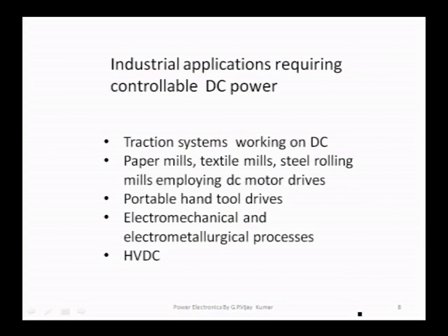So, that is why we are studying phase controlled rectifiers. If somebody asks why you are studying all these things, phase controlled DC power, these are required in industrial applications where you need to control the DC power. We cannot have applications working only on a constant voltage. When you need a variable DC voltage, we have to go for phase controlled rectifiers only. The beauty of the SCR is we can fire the SCR at a desired firing angle. That is the beauty of SCR.